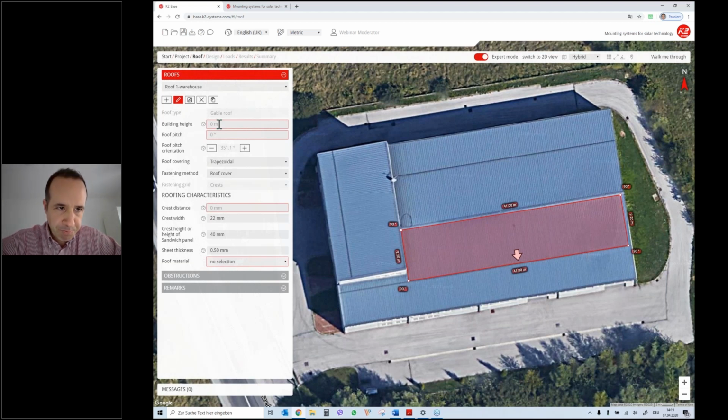So if you're an installer, you have to do the building survey in order to be able to enter this data, because if you do it by heart or feed it with incorrect parameters, then the installer actually installing this mounting system will not have the real-time circumstances. The calculation and the document printout won't be in agreement with what's going to be the case on the rooftop itself. So this data has to be really 100% accurate.